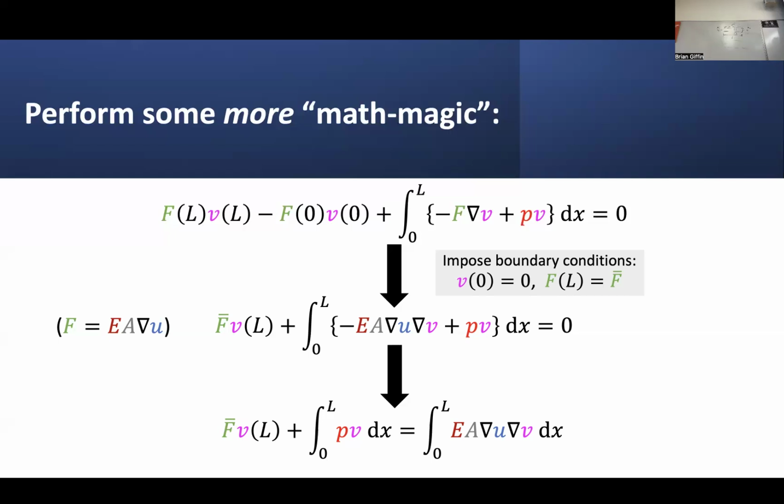We've actually included whatever external force boundary conditions directly inside of this expression. We don't necessarily have to enforce any of these extra boundary conditions by setting some unknown constants of integration that we would determine in the process that we would normally adopt when we were solving the strong formulation of this same problem. So we've actually incorporated any of our force boundary conditions directly in this statement of equilibrium.